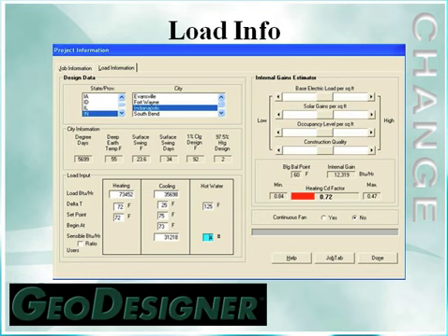If we're going out on a project on an older farmhouse, single pane windows, very little or maybe no insulation in outside walls, I may adjust that to the lower side, and we'll see the building balance point go up a little bit. I also do look at it if I'm planning a new construction job with super insulated panels or insulated concrete form walls that has a very high construction quality, I might adjust that up 1 or 2 set points, and then my building balance point will go down slightly.